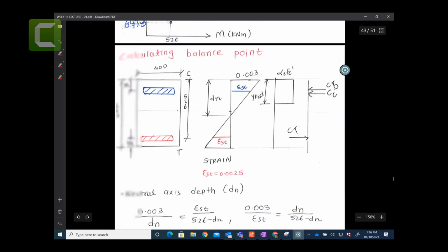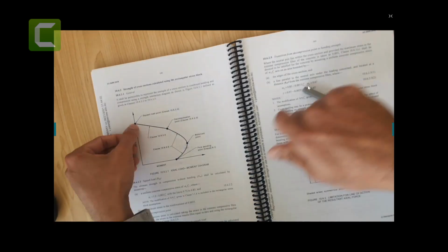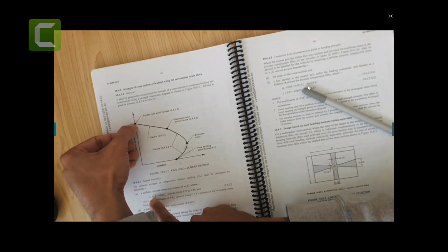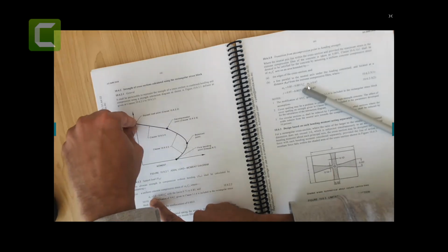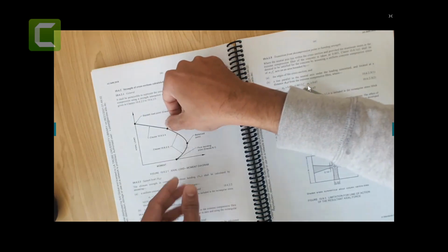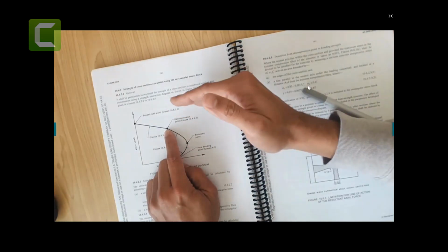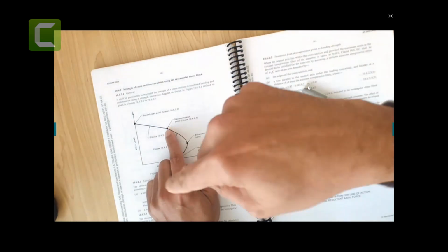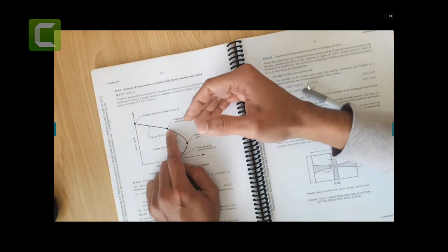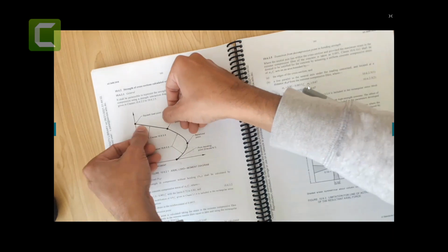Okay, now here we are talking about this balance point. We have done this one, which was quite easy: alpha 1 f'c times area of the concrete plus fsy times As. The stress in the steel and the stress in the concrete, we take both steels and we find the zero moment. We found all the forces, this is the clause that we're going to use. Forces in the steel, forces in the concrete, sum them to get the force. Moment is force times the distance to the plastic centroid for the steel, and force of the concrete times the distance to the plastic centroid. That's how we get the moment. And this is a straight line, by the way.